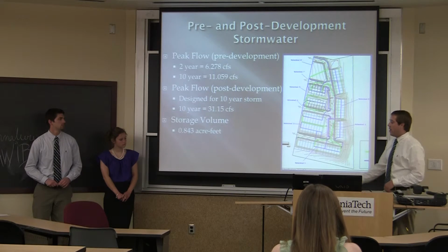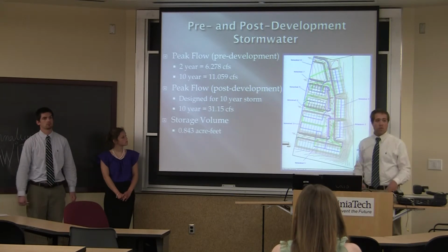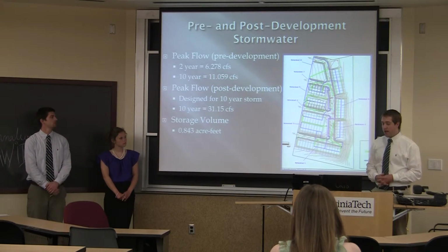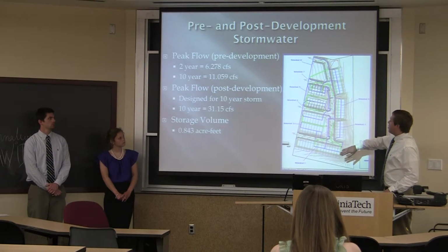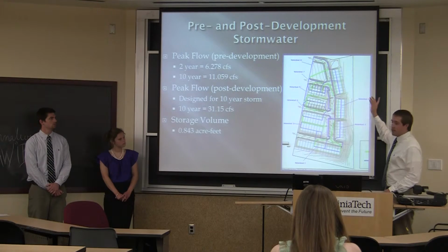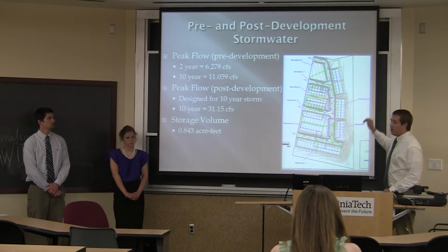And then finally, we found a storage volume for our site in order to mitigate all the stormwater coming from our site. We actually aren't retaining any water on site. Our stormwater management plan has it all flowing to an existing detention basin off-site to the northeast.